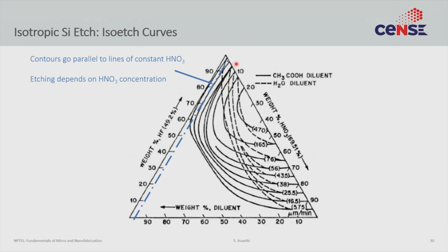Now this shouldn't be very surprising to those of you who have seen this happen before. Remember, two reactions need to happen in series. We need to oxidize and then we need to etch the oxide. In an equilibrium system, these two rates must be equal. So the total etching rate is equal to the slowest step etching rate. So the slowest step decides.